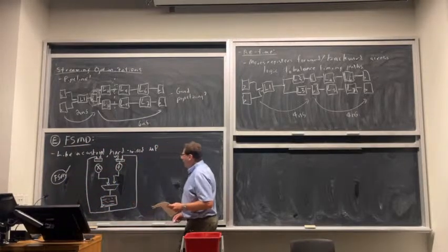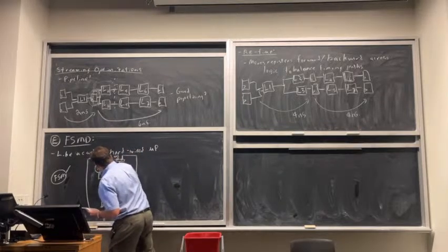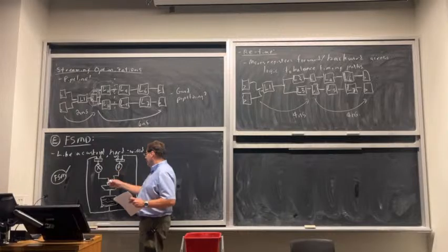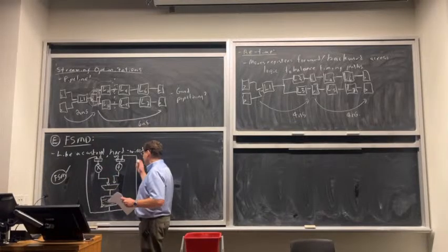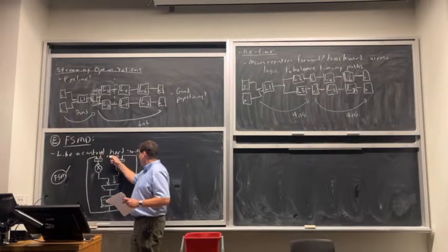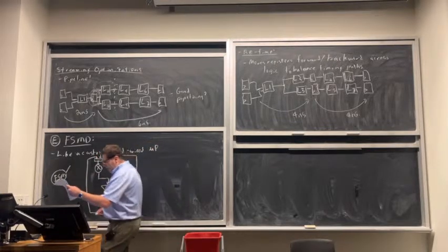This data path is a lot like a processor data path. I've got a multiplier, an adder, I pick which one, I can store things in the register file, take things out of the register file, and also send new inputs in 1 or in 2 into this data path, but I need to control it.